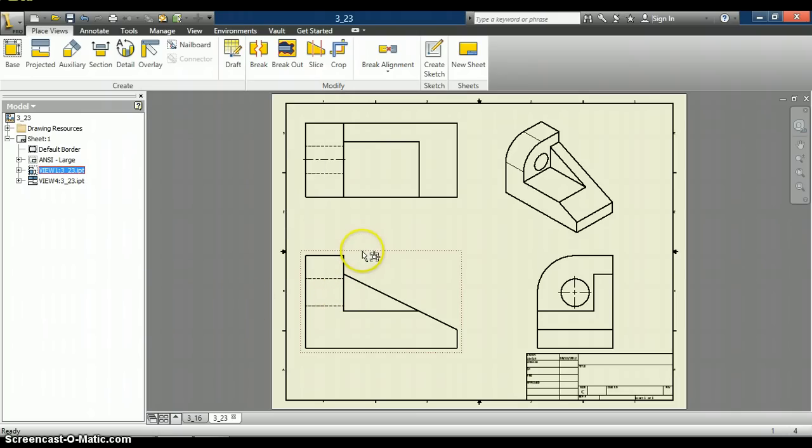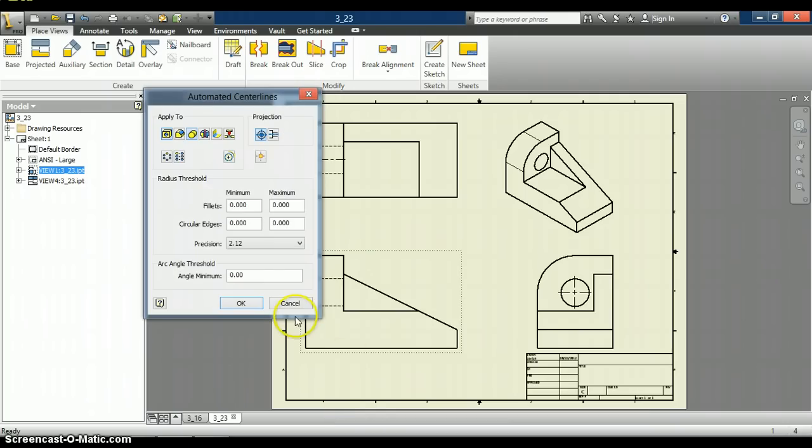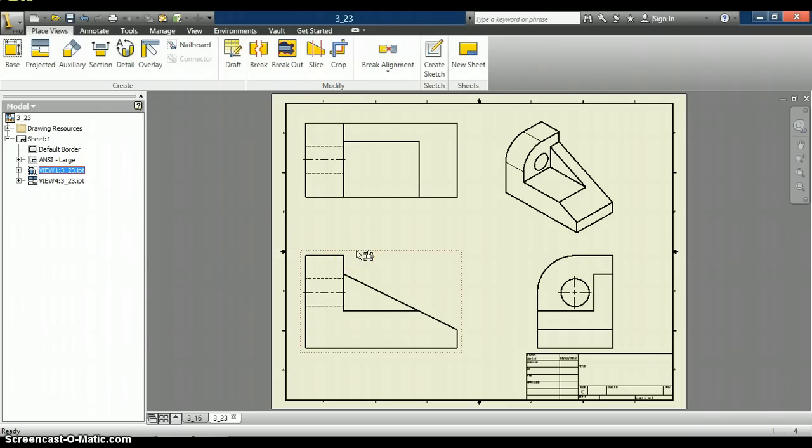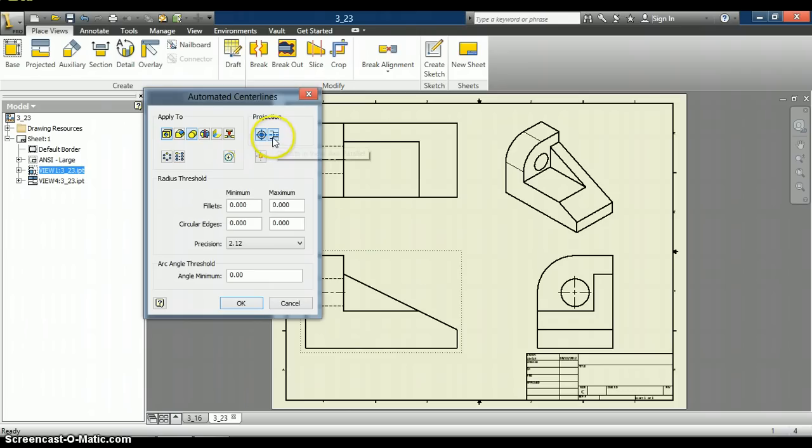it doesn't do anything. So I didn't quite do it right. So let's try that again. Automated center lines. Features. Let's try that one there, maybe, see if that gives us the same option. There we go. So in that case, because I didn't have the objects in view axis parallel, so I had parallel axes down here, that's the reason it didn't insert it.